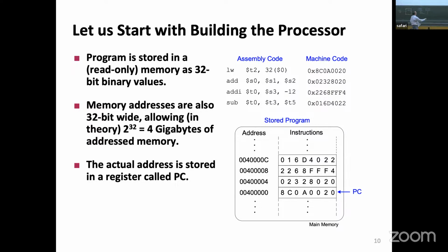That's great, because I have one of my operands coming out here and the other operand coming out here. Now I can take this unit that can do interesting things with them, which was the ALU. I'm just going to turn it this way around. So I have this kind of unit, ALU, and it has 2 inputs, A and B. This is 32 bits, this is 32 bits. The result at the moment will be 32 bits. And I'm going to simply connect them together. Okay, there you go, ALU.